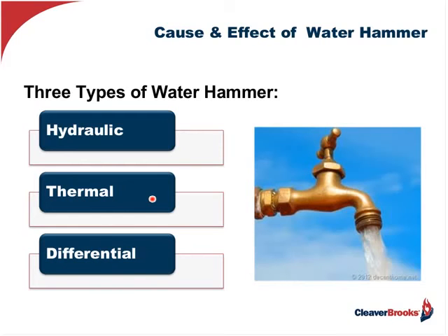Let's say that we've got steam tracer piping from various areas dumping into a common return at different temperatures. What happens is, as soon as that biphase hits the common return condensate line inside the liquid, the steam bubbles within that condensate collapse, forming a vacuum, if you will, or a void, and all the water begins to rush to that particular point. It's called thermal water hammer.